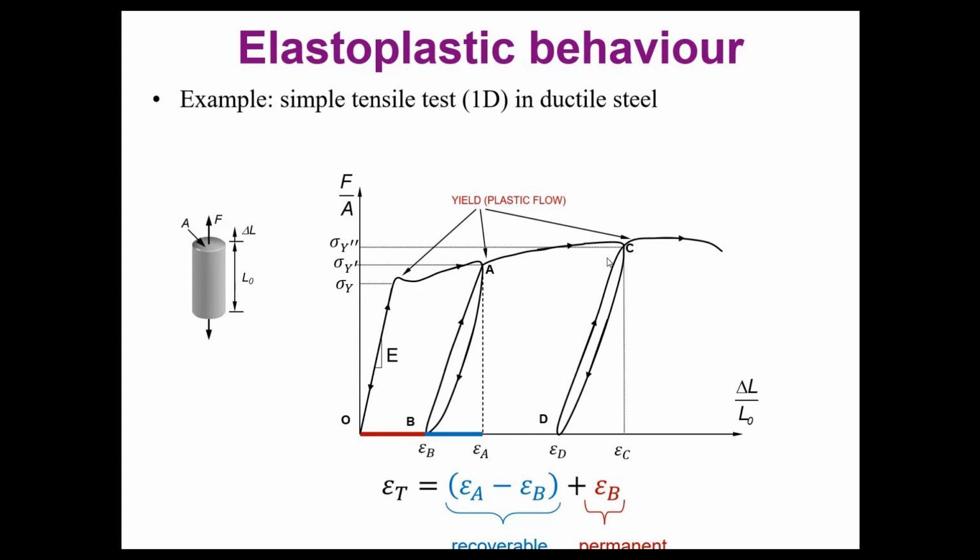So this steel is becoming stronger and stronger when you unload and reload the bar, because you are increasing the value of the plastic strength that establishes the new yield limit for the elastic regime.